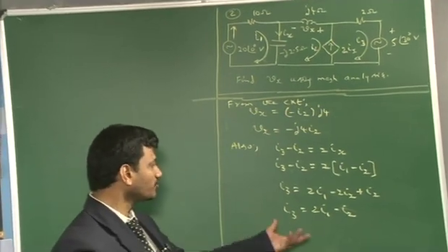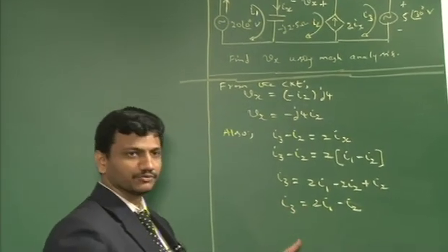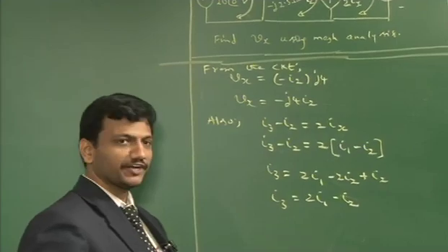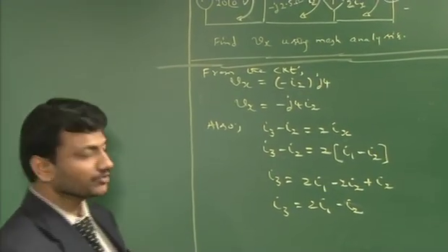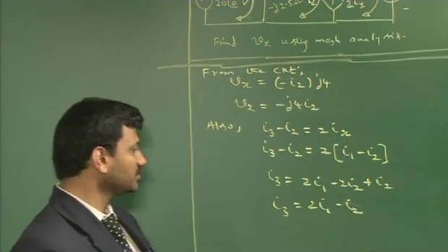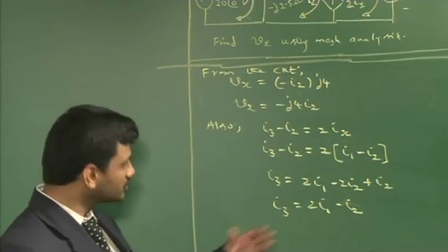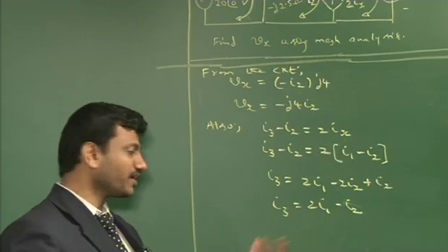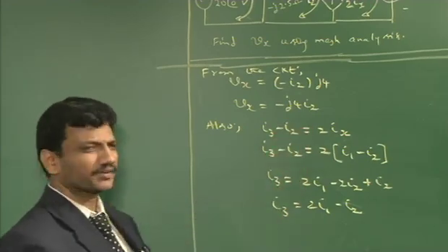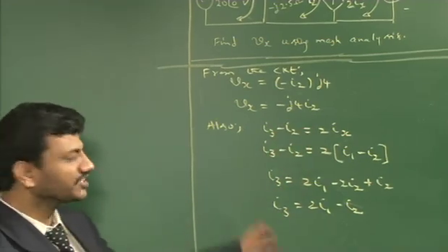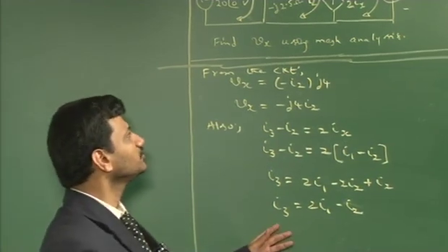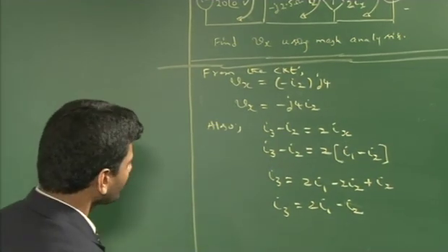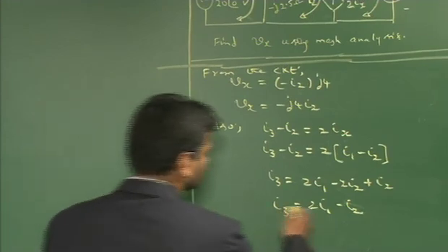So, instead what you could have done, you could have written this in terms of I2, then substituted for I2, then I2 gets eliminated, and with the elimination of I2, what you will calculate first is I3 and I1, then using this relationship you come back and calculate I2, then substitute here. So, it will be one step extra. In this case, we are doing it directly by eliminating I3, by doing the substitution for it, right. So, this is the result of the constraint equation.